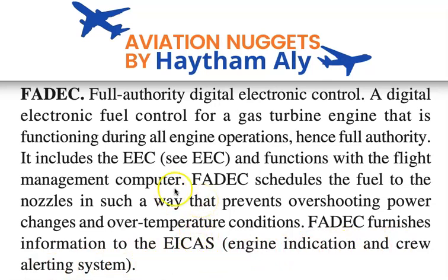So again, I need to tell you, the FADEC, or the EEC of the FADEC, which is the heart of the FADEC, must be connected to other aircraft systems. There is essential communication with the FADEC. The EEC must be essentially communicated with some essential systems like the throttle lever angle. From the throttle lever to the EEC there is a direct communication.